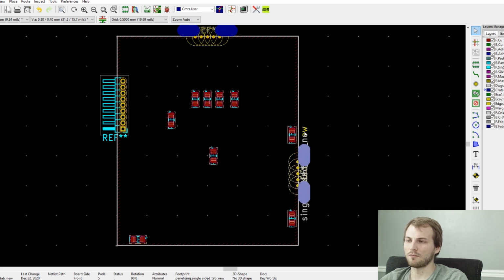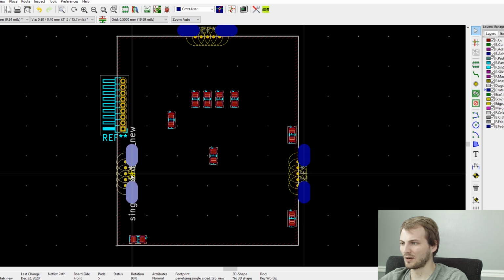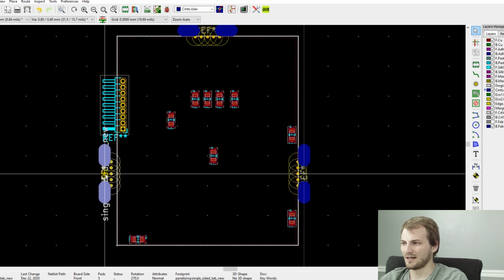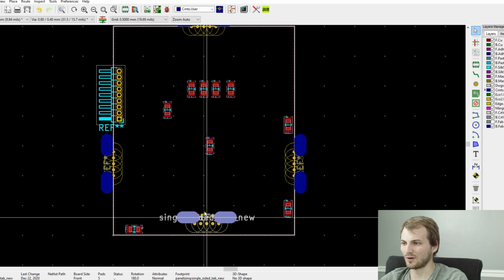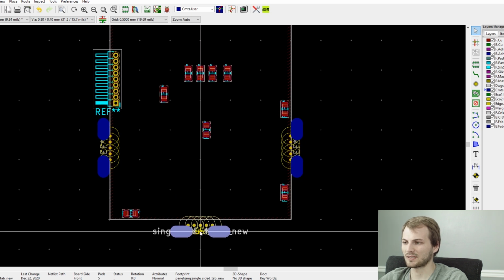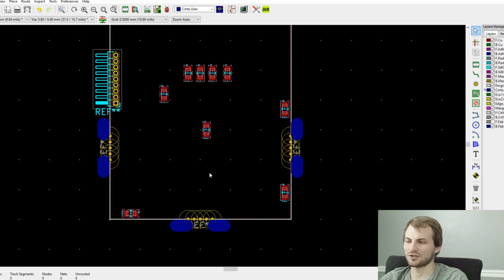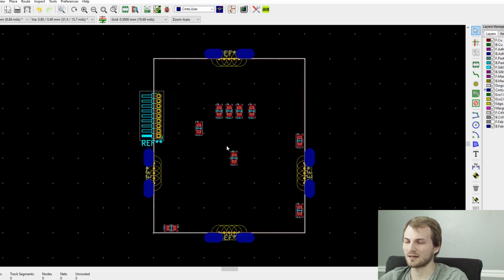So this is more than 15 millimeters, but on such a small and light board, I don't think it'll be an issue. A lot of this is experience from doing it a decent bit, and honestly, guess and check. If you do one and it's too flimsy or it's hard to deep panelize, you want to make changes for the next time you do it, obviously. But on a small board like most people will have, as long as you have one tab roughly center on each board, that should be fine.